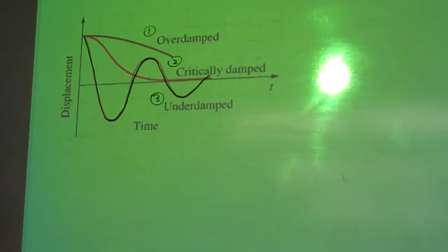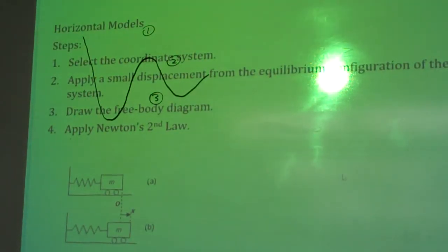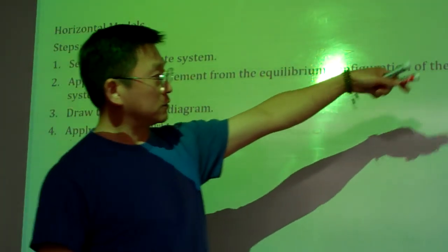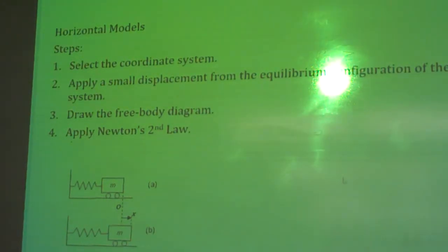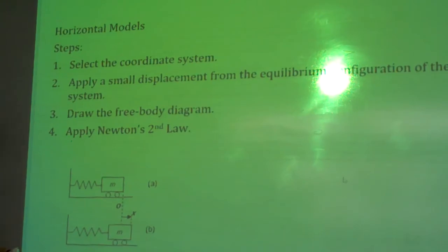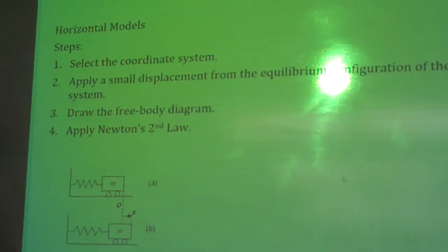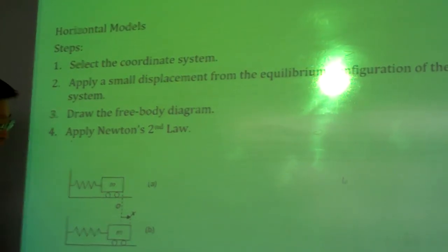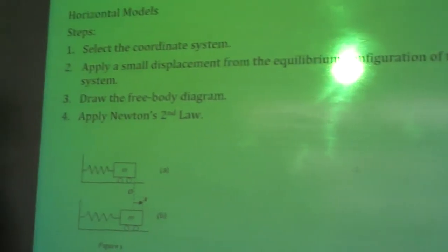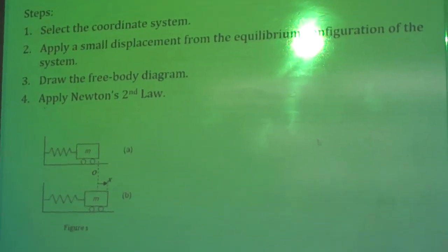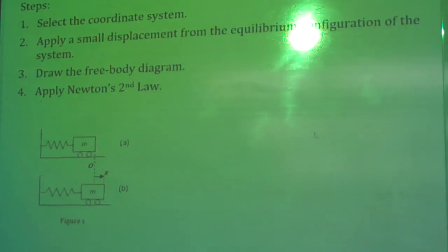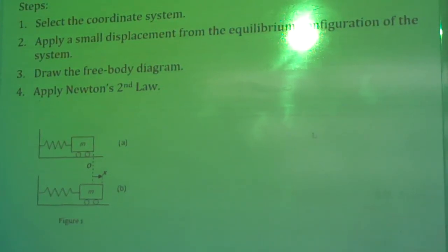Okay, with this in mind, we can move on to the next slide, which is to exercise our formulation of the equation of motion. For this undamped system, here is the procedure I highlight. The steps are this: you simply define or pick the degrees of freedom. For this one, there is only one mass block, so that is one degree of freedom. For your exercise, you need to define your degree of freedom, and usually the definition is pretty straightforward.